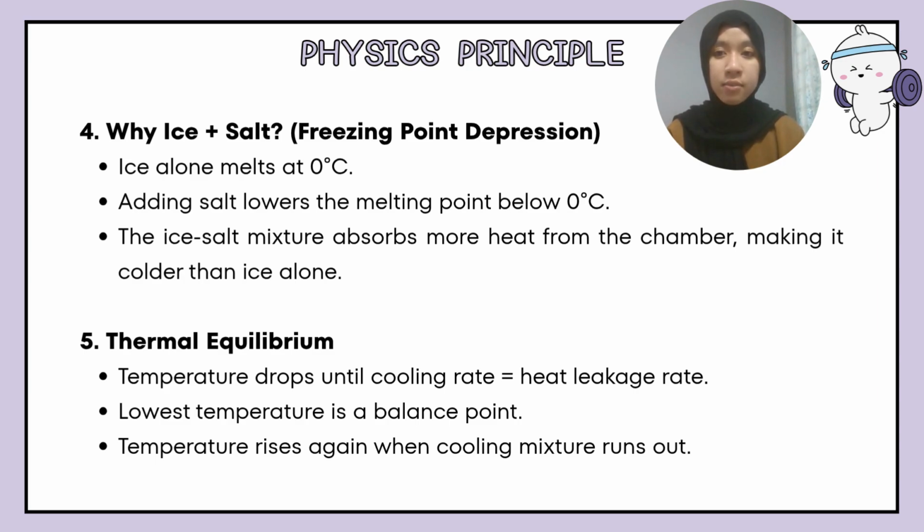And fifth, thermal equilibrium. The temperature inside drops until it reaches a point where the rate of cooling equals the rate of heat leaking back in. That lowest temperature is the balance point. Once the ice-salt mixture runs out, the temperature slowly rises again.